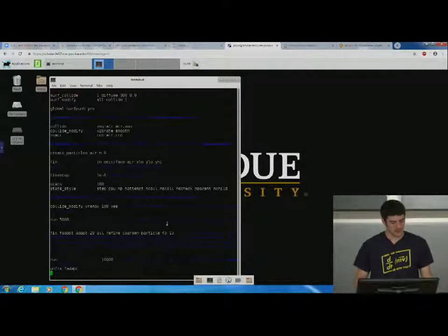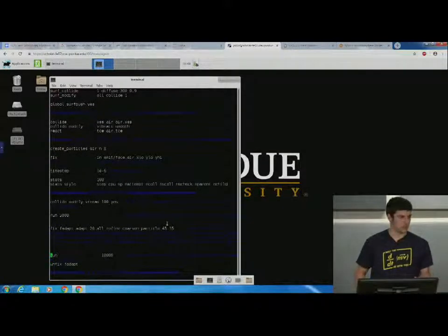So then the next thing is a bit strange, not necessarily so intuitive, but I like to do this. When you start off your problem, naturally things are not yet realistic conditions. Either you start off with a complete vacuum, or with some particles that aren't representative of the actual flow. So what I do is I call this unsteady flow. I initialize the problem by basically running the simulation before I'm taking any data, just to make sure that things are set properly before I start taking the samples.